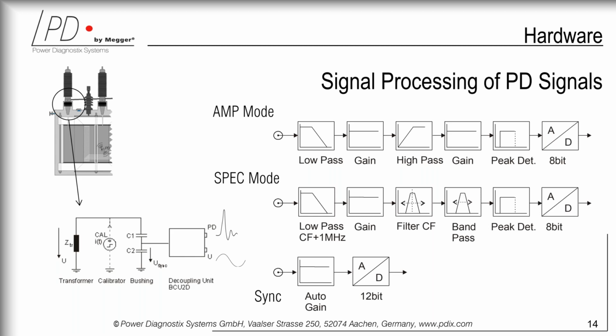partial discharge. Usually they look at 100 or 200 picocoulomb, they inject that to the bushing, and then of course they want to read the same amount through the bushing tab, and eventually the instrument should be able to do that. And so, in order to do that, certain calibrators are being sold and used in order to properly do the test.